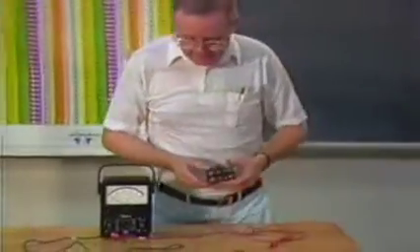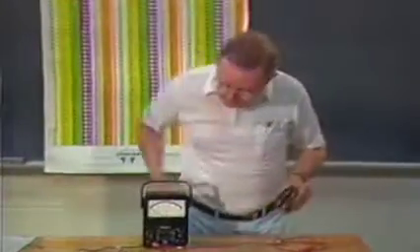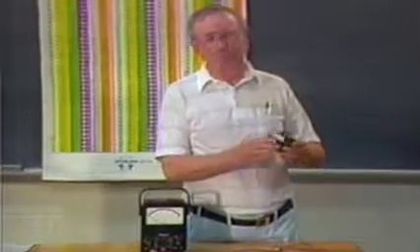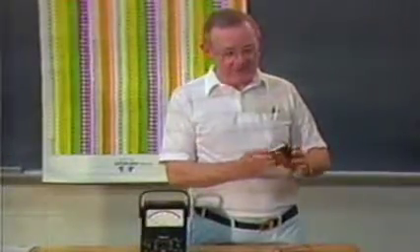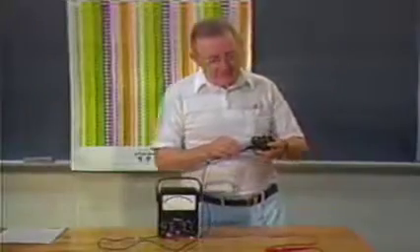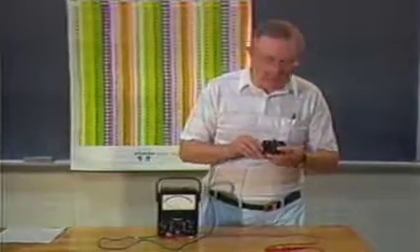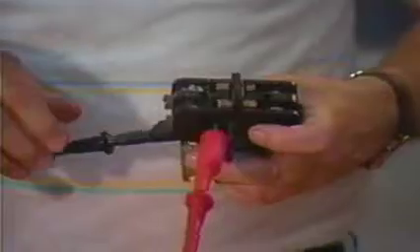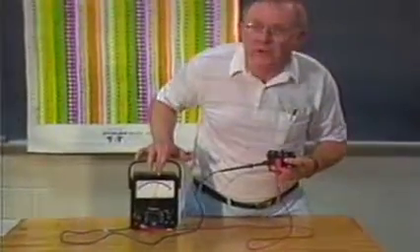Now the coil circuit might be checked in a different manner. To check the contact circuit, we checked it on the R times 1 scale. Now we'll have to experiment around and find out how much resistance is actually in the coil circuit. Now we'll fasten one lead to one side of the coil circuit on the relay. We'll take the other lead and fasten to the other side of the coil circuit on the relay. This is the information that we want to know about the relay.